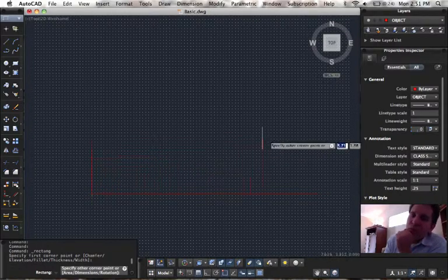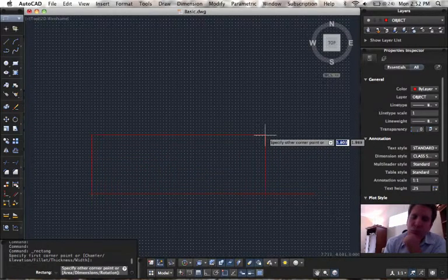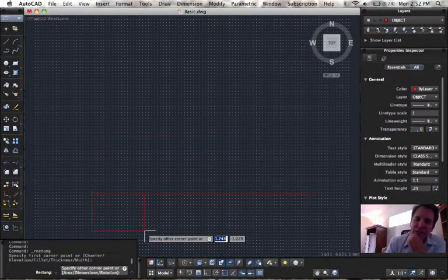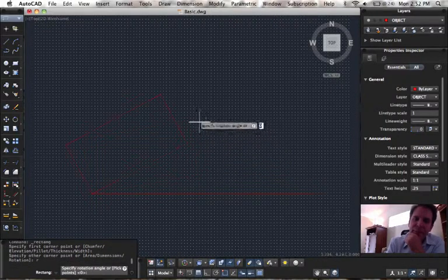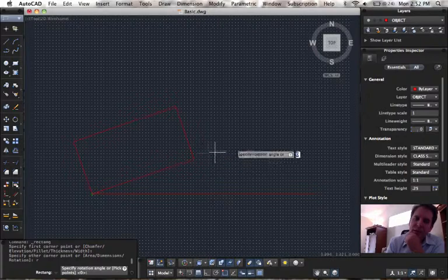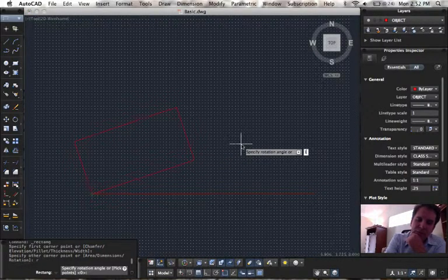And this rectangle is going to be rotated a bit. So we'll notice one of our options here is rotation, and that capital R means we can hit R to select that command. So I'm hitting R and enter. For our rotation, you can see as I move my mouse, our rectangle is rotating on our pivot point, which was our beginning point there. We're just going to stick with our 12 degrees, so I'm going to hit enter for 12 degrees.